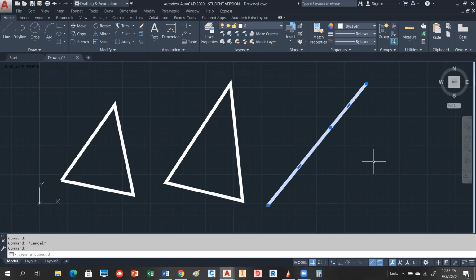Now, a little bit later on, we're going to talk about a command called lengthen, which kind of does the same thing, but instead of actually attaching a segment, it would just push this guy up. So there's a bit of a difference, okay, between the length option in the polyline and the lengthen command, which we'll get to later. Is everybody okay with that so far? Any questions?